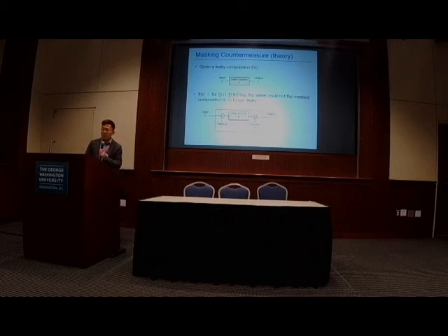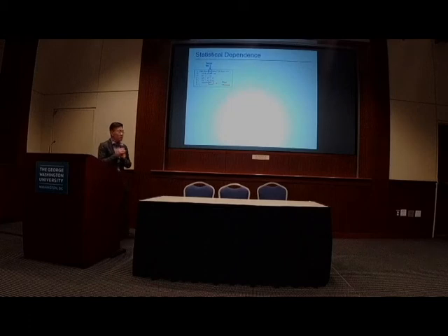Of course, this works only if F is linear, right? In practice, most of the crypto algorithms are not linear. So what ends up happening is that you have to hire some experts to rewrite your design. So here is a more concrete example. Let's assume that this is a piece of C code with 3 Boolean inputs. I1 is the secret. I don't want you to know whether it's logic 1 or 0. But you can observe the power consumption fluctuations, which is related to the logic bits in N1, for example.